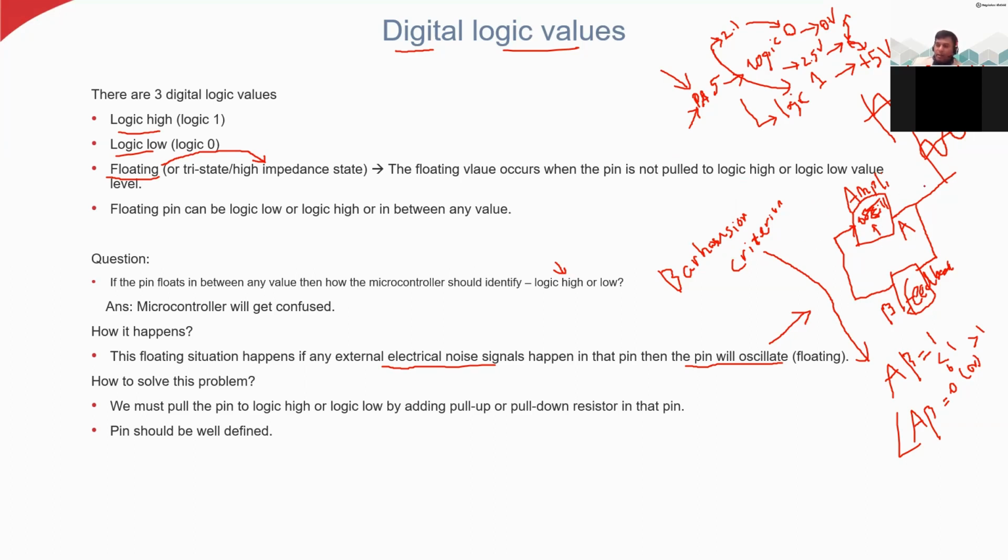The oscillator is producing oscillations because of the thermal noise. That is the concept, or working principle, of this oscillator. The same is happening here in this microcontroller. A microcontroller has so many pins. Sometimes there may be some thermal noise or electrical noise happening in a pin. Because of this electrical noise, the pin is floating. It's not at a stable value. It's just moving back and forth between 0 or some other value and the high value.